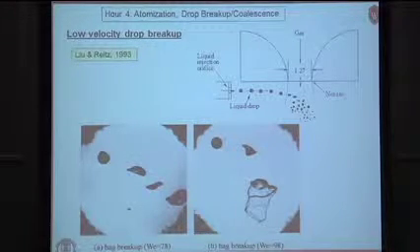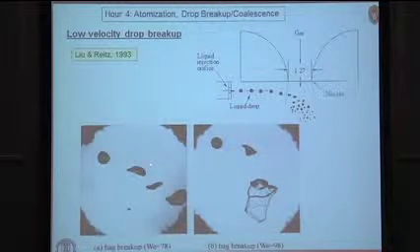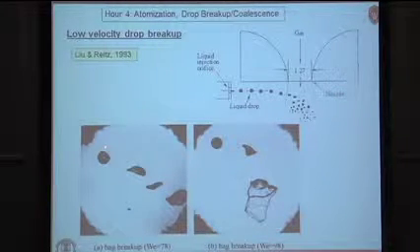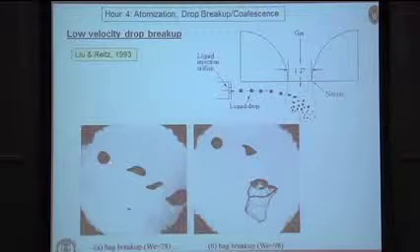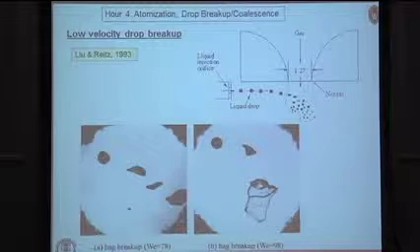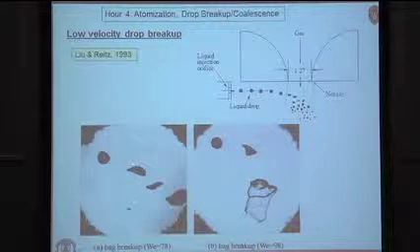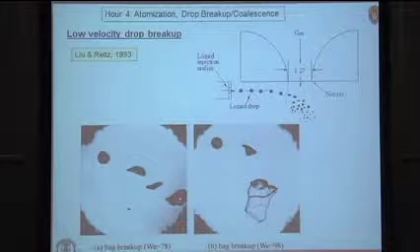And you can see that for relatively low Weber numbers, the droplets flatten. And that's because, if you think about it, as they encounter this gas flow, this used to be a spherical droplet. You can see it just started to interact with the gas flow. There is a stagnation point at the north pole of the droplet where the pressure is higher and you have a flow around these droplets. And at that stagnation point, the droplet is flattened. And you see it becomes flattened here.